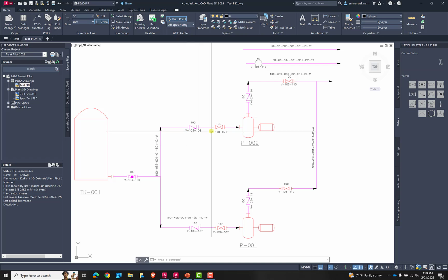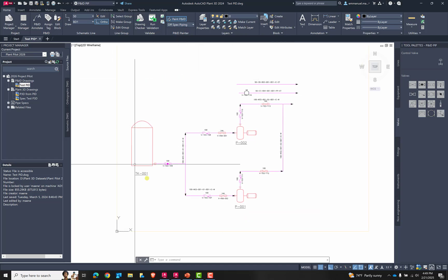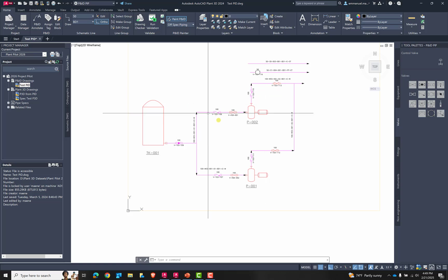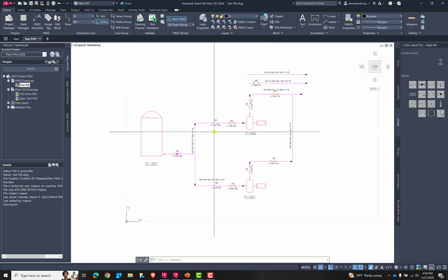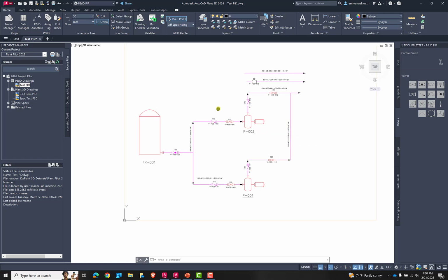Now, please note that this P&ID painting option is only visible when you want to print it or when you want to convert this drawing to a PDF. It is not available when you want to export your drawing into AutoCAD, because these related settings are inside the database. So when you perform that option of exporting to AutoCAD, these colors will not get exported.